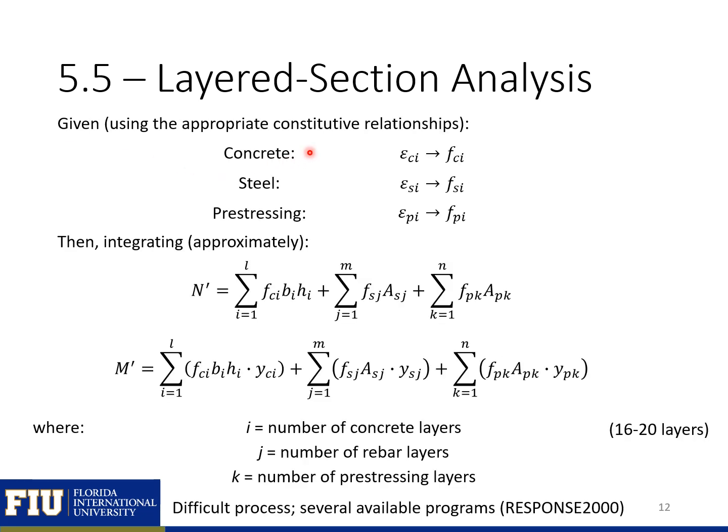We can use appropriate constitutive relationships, stress-strain relationships, to relate the strain in the concrete, steel, and pre-stressing to the stress in the concrete, steel, and pre-stressing. So at this point, we would have the stress in each one of our concrete, steel, and pre-stressing layers.